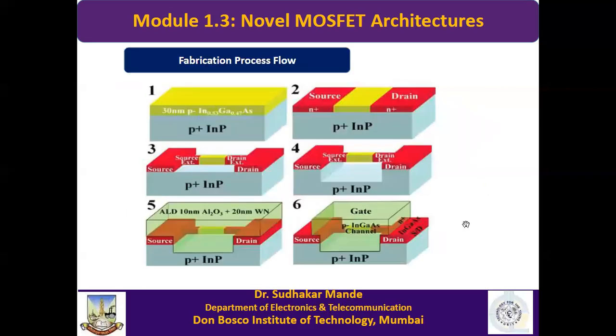Right? Yes, sir. Now let us see how it is fabricated. There are various types of GAA FET. Here I'm showing just the fabrication process flow for an indium gallium arsenide channel GAA FET. See, first we take highly doped P-type indium phosphide, that is the substrate.